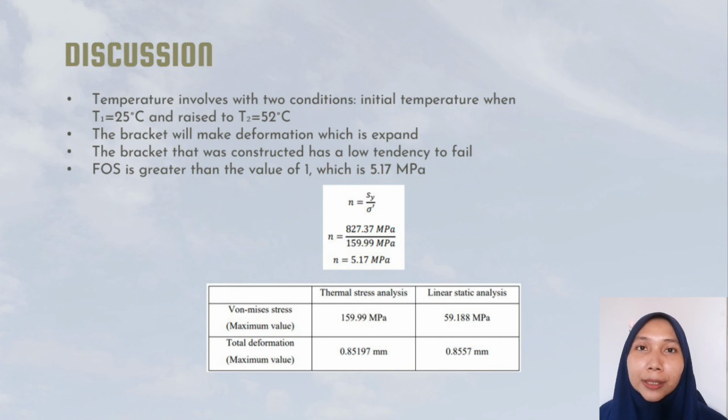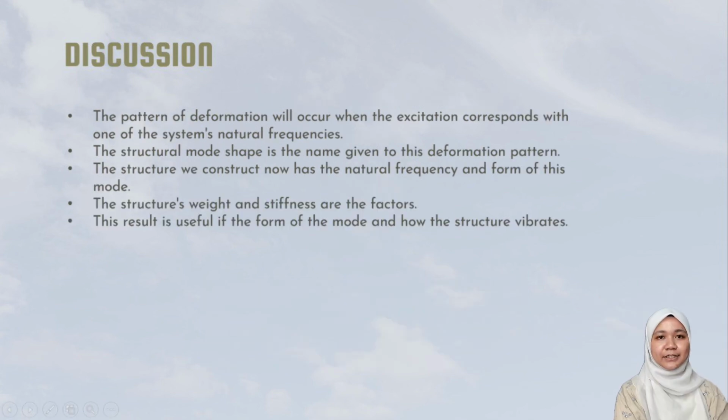The pattern of deformation that will occur when the excitation corresponds with one of the system's natural frequencies is called the structural mode shape. The structure we construct now has the natural frequency and form of this mode.